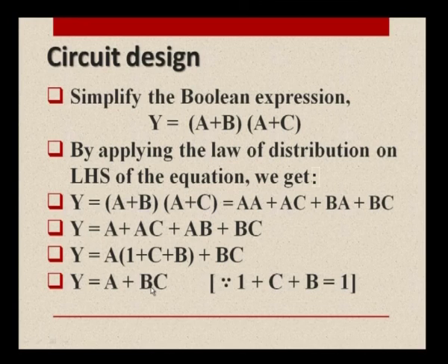When it comes to circuit designing, we will be using integrated circuits. I have already introduced how the gates are embedded in IC chips. The number of gates reduced will have an effect on the number of ICs reduced. If the number of ICs is reduced, the power consumption is reduced in the circuit design. So, like a chain reaction, one after the other, advantages get added up. Finally, we will be able to reduce the cost of implementing the given expression into circuitry.